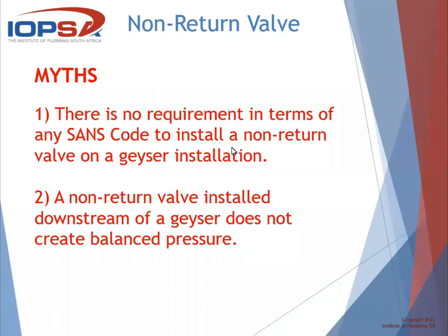Yeah, and I think also on top of that is the fact that you will have a metal deterioration in that valve, which will obviously also go into the water. Yeah, you could have damage to the seat or the flap.